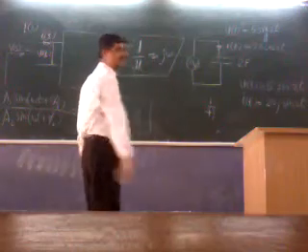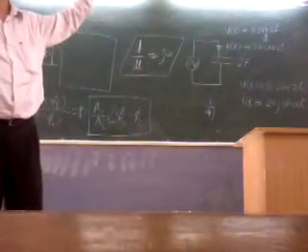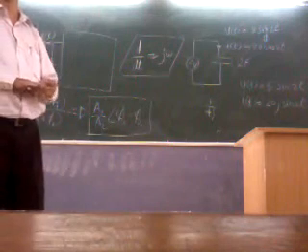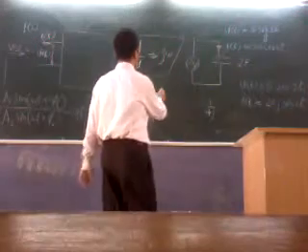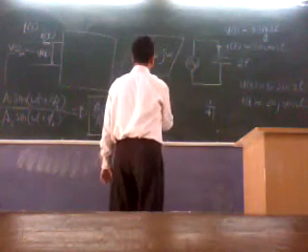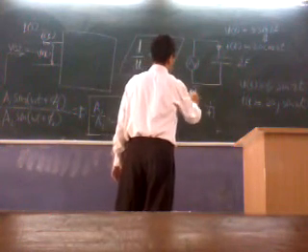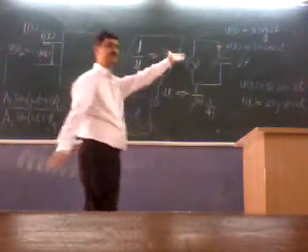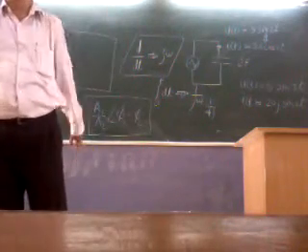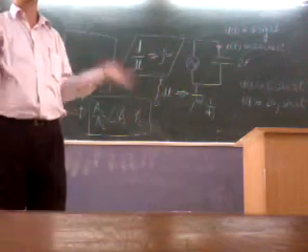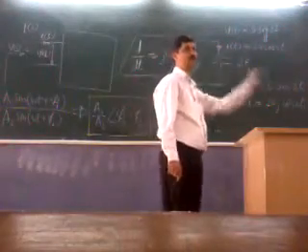So for sinusoid analysis, the differential operator is a scaling operator. And what will be the integral operator? The integral from 0 to t of dt, that operator is the reverse of differential. Since differential is multiplied by j omega, integral is divided by j omega, or multiplied by 1 upon j omega. And from that point of view, the impedance of a capacitor becomes 1 upon j omega c.